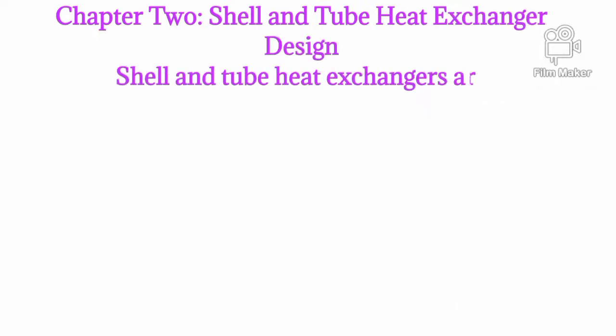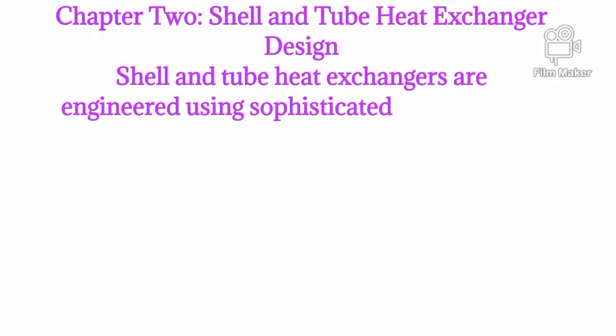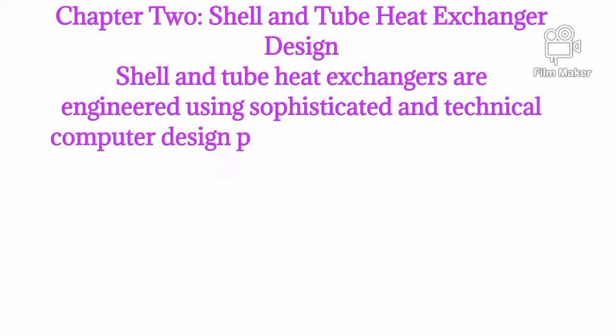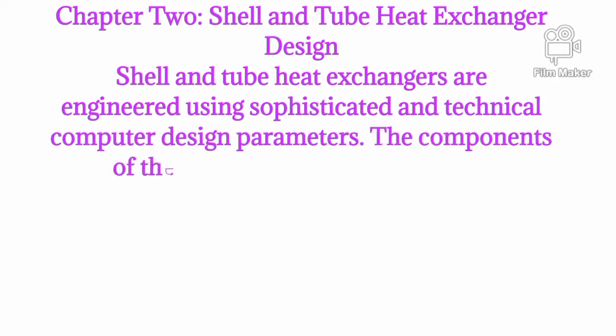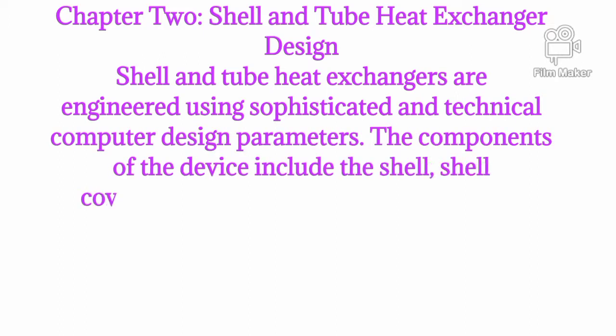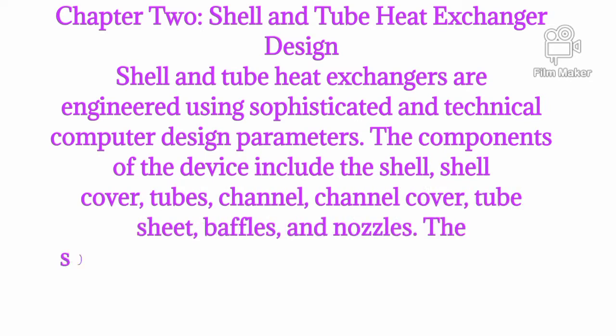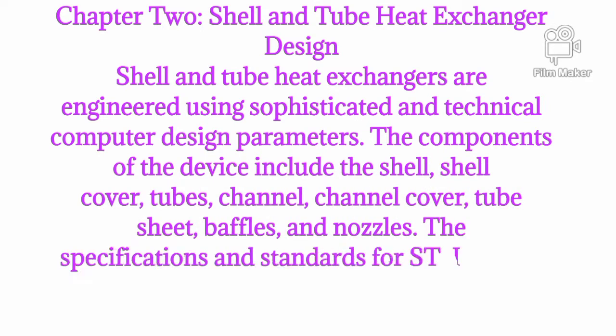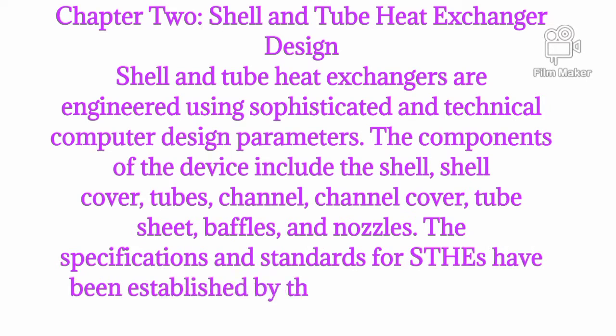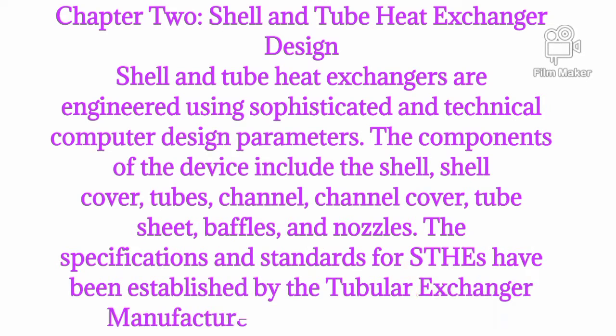Chapter 2. Shell and tube heat exchanger design. Shell and tube heat exchangers are engineered using sophisticated and technical computer design parameters. The components of the device include the shell, shell cover, tubes, channel, channel cover, tube sheet, baffles, and nozzles. The specifications and standards for STHEs have been established by the Tubular Exchanger Manufacturers Association (TEMA).